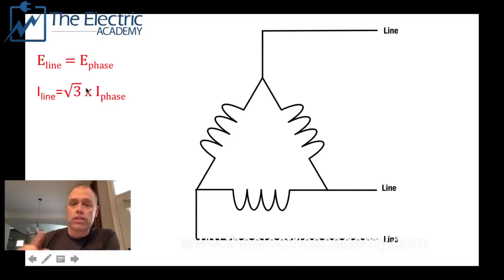Now, some of the advantages for a delta system is the motor torque. It's got high motor torque. It can handle it because it's got a higher current it can handle. It's more efficient. The protection is generally fairly simple. They're set up for heavy-duty applications. They're great for transmissions. You'll often see them set up as a delta Y transformer. When you are sending them across lines for transmission, they prefer to have the delta configuration, even though the current might be a little higher, because you only require 3 wires.